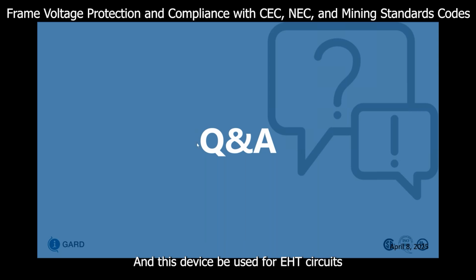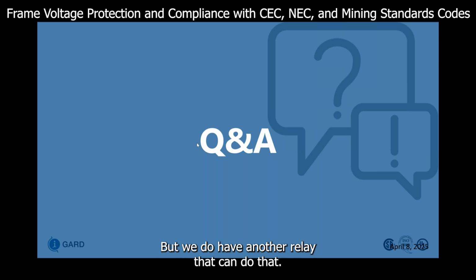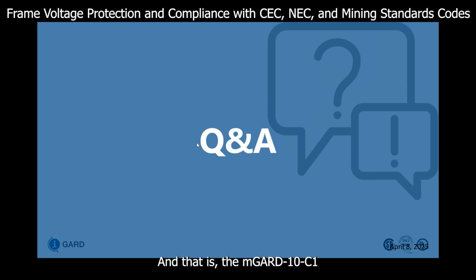Can this device be used for EHT circuits where we need 30 milliamp detection? I believe the relay goes down to 500 milliamps. I don't think it can get down to 30 milliamps, unfortunately. But we do have another relay that can do that, and that is the I-Gard 10C1. If we use a TXB sensor, we can get down to 10 milliamps using 3 turns through the CT, or we have a setting for 30 milliamps. What's the max adjustable setting? I think off the top of my head, it is 1200 amps.